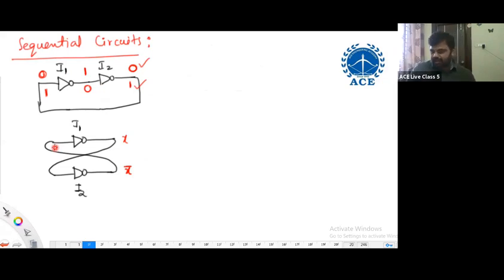You might have studied a PFD circuit, a charge pump circuit, voltage controlled oscillator, and a divide by network. That is a PLL, phase lock loop. Understanding? PLL we are using as a clock generator. In our processors, in our IC, we are using a PLL which is generating the clock.